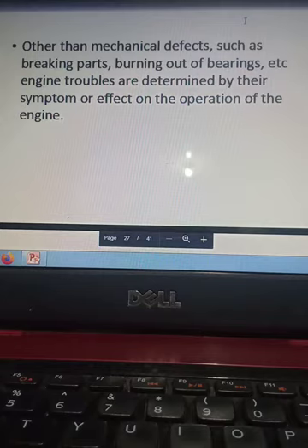Regardless of the number of cylinders incorporated in an aircraft engine, when a correctly proportioned charge is compressed and properly ignited in each cylinder, the noise of the exhaust will be heard each time this event takes place in the cylinder at the opening of the exhaust valve. So if your engine is normal, there is no problem, its operation is smooth, and you can tell the timing of the exhaust, as the firing just follows in sequence, right?